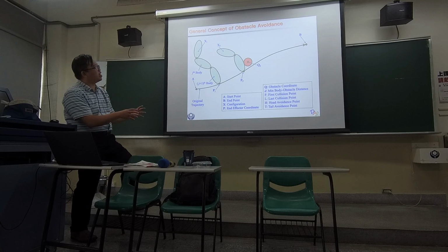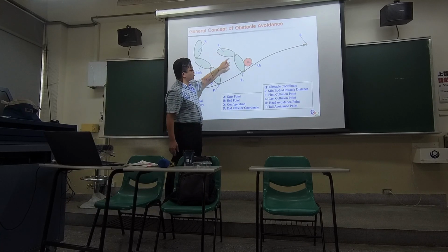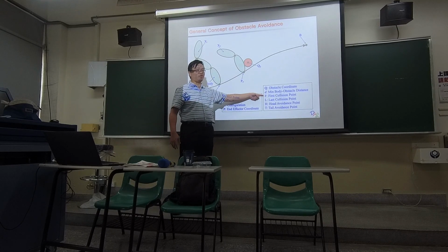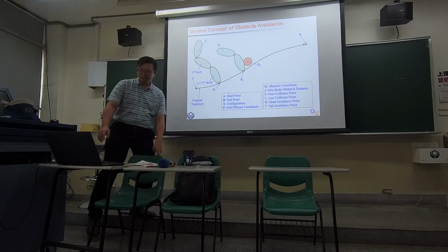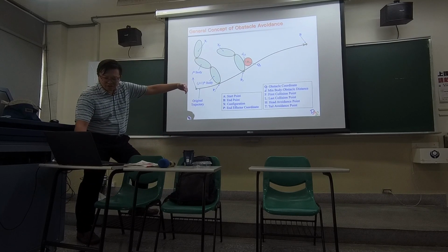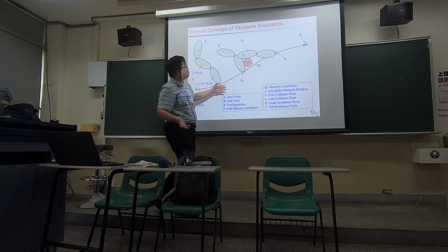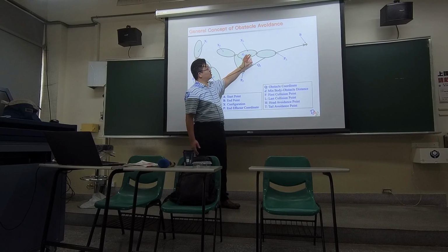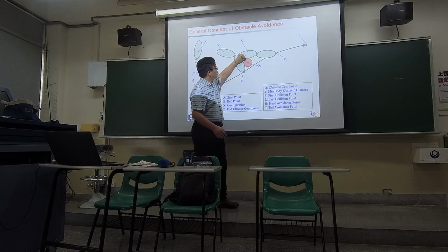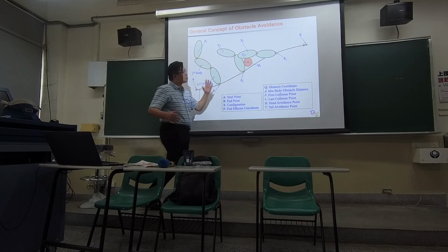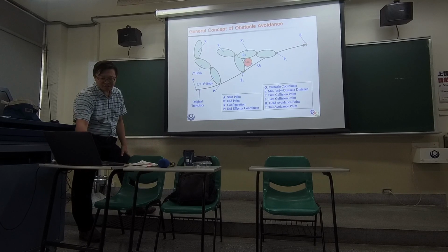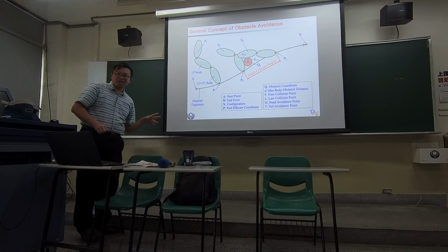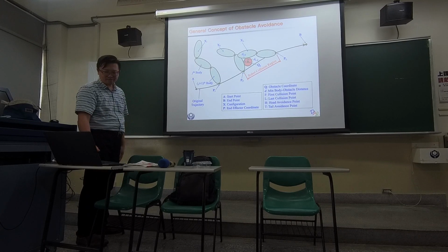At a certain moment when your robot configuration is having the first contact, I'm calling this the first collision point. So F represents first collision. And the robot keeps moving until it reaches a certain configuration like this. If this is the last configuration that has collision, the next moment it moves, the collision finishes. So I have a first point and a last point. I define this as the robot collision region. We want to avoid this part.